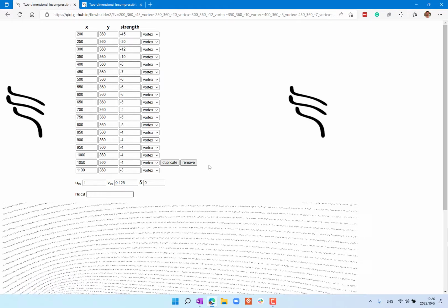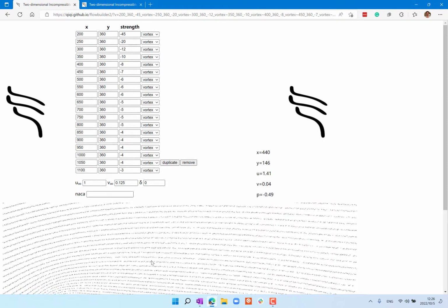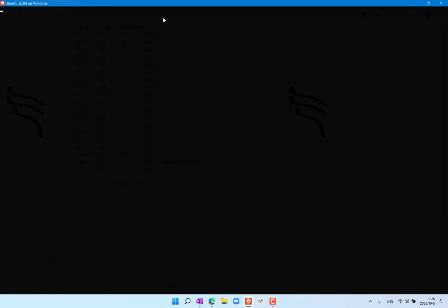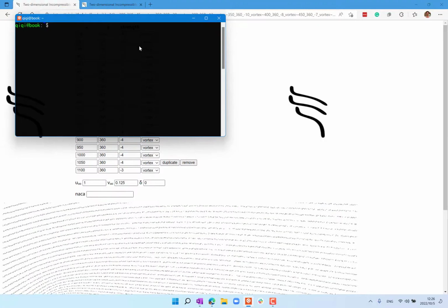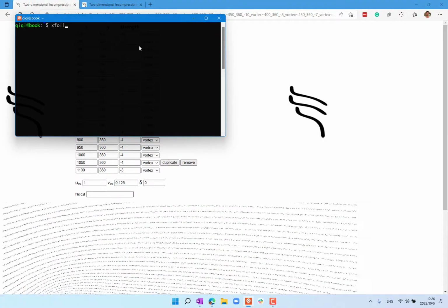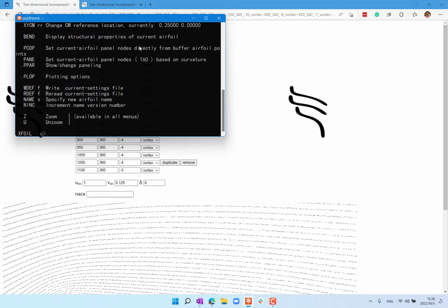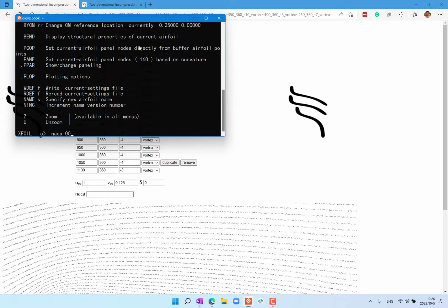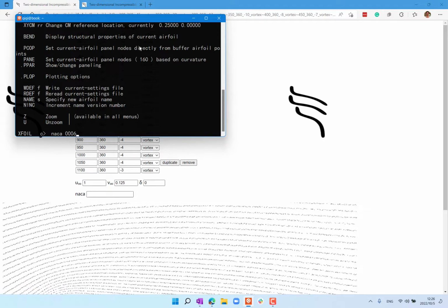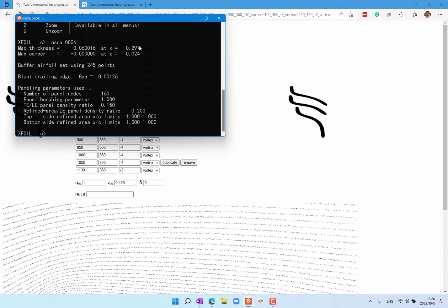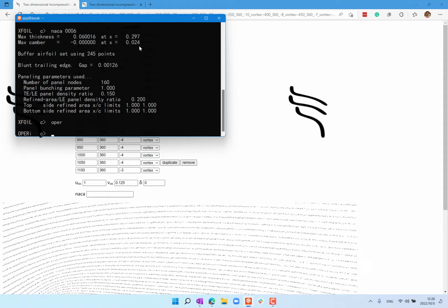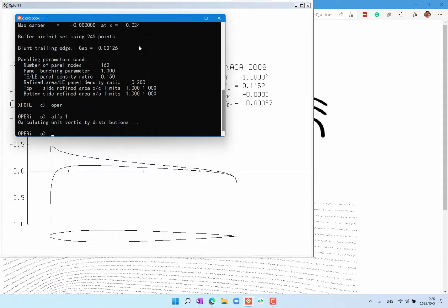Just to end the lecture, I'm going to tell you this is actually definitely the most useful tool for designing airfoils. It's called XFOIL. The easiest to illustrate is using a very thin airfoil, NACA 0006. It's very thin, right? And put it at 1 degree angle of attack.